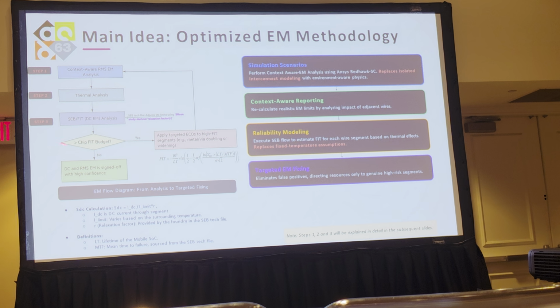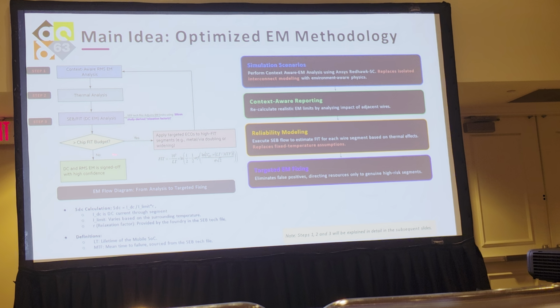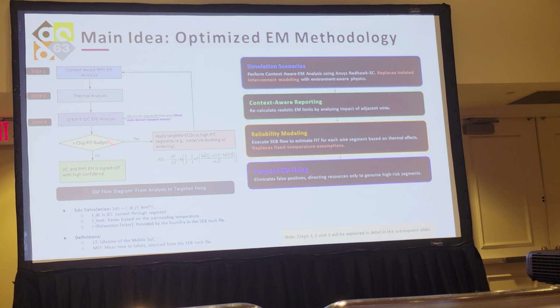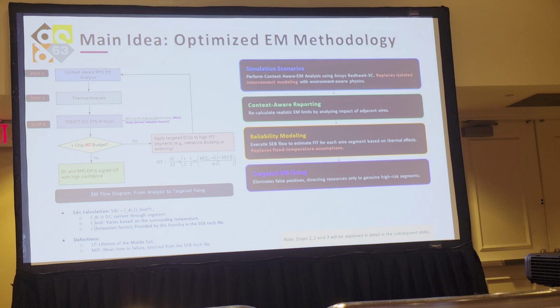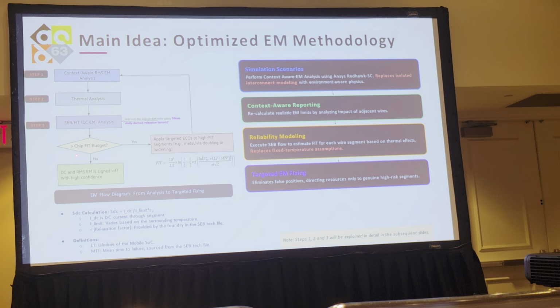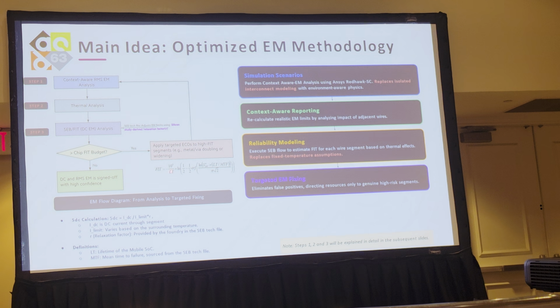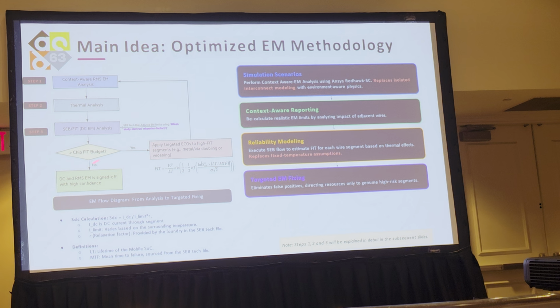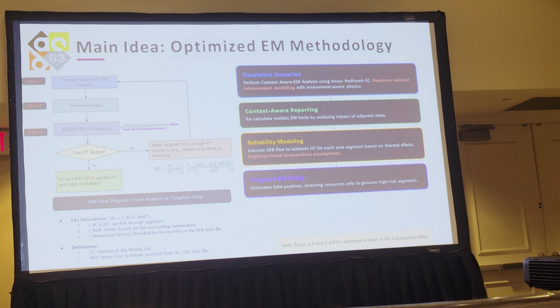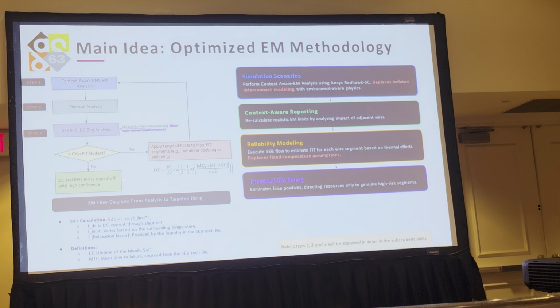For a full SoC level, we'll have one particular chip budget, which I'll explain in the next slide. If we violate this budget, we have to fix those violations, and if we are within that budget, we can safely waive those DC, RMS, PG and signal EM violations.